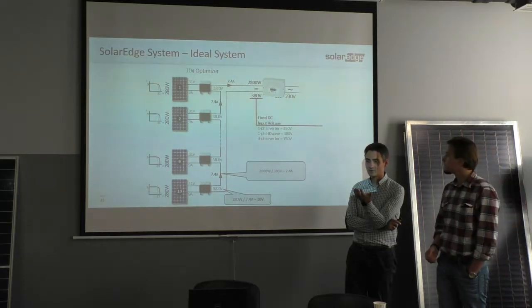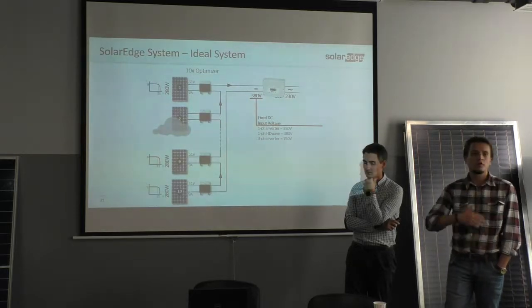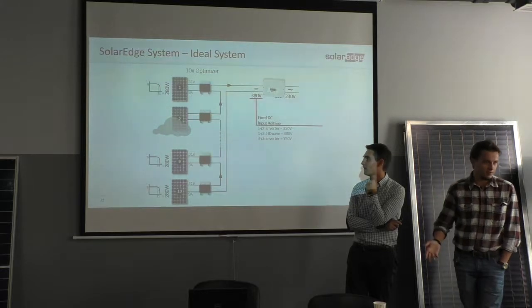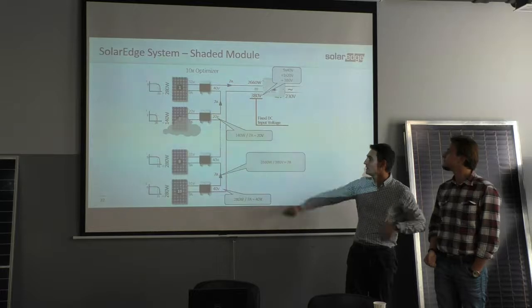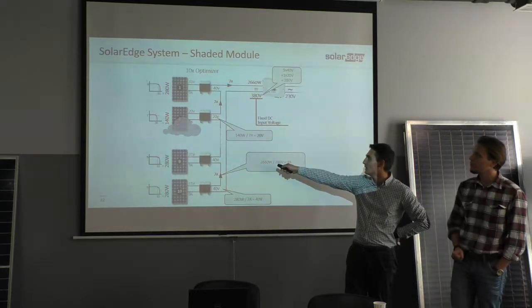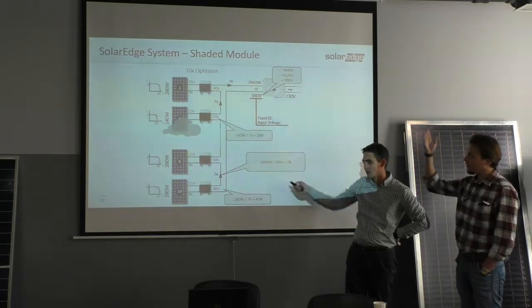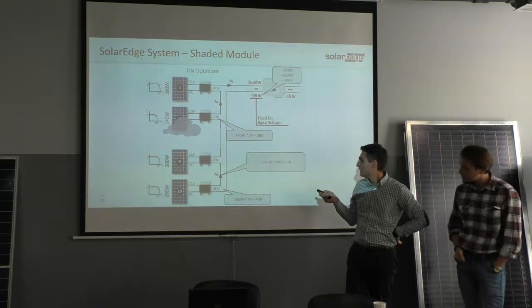But in real life, there is no situation where each module gives the same output. So let's analyze a situation where we have some shading. Let's assume that this module gives us 140. So the total power is 2660.